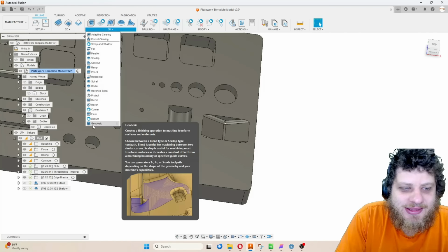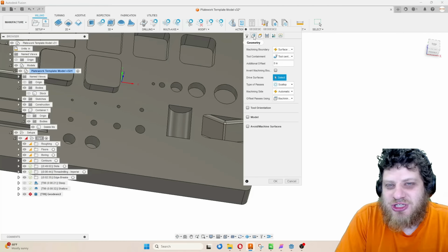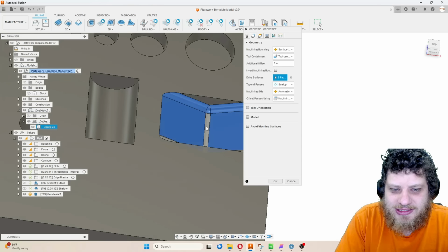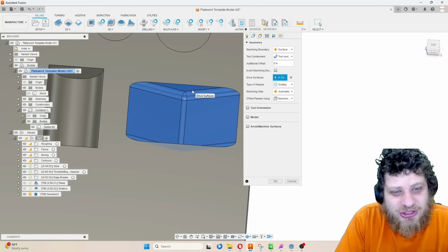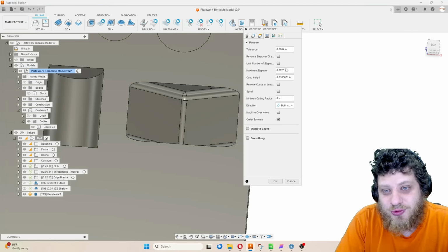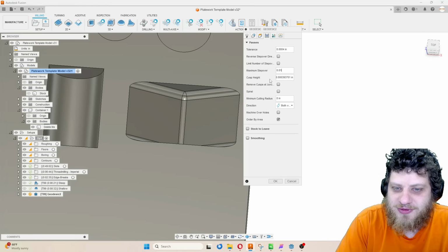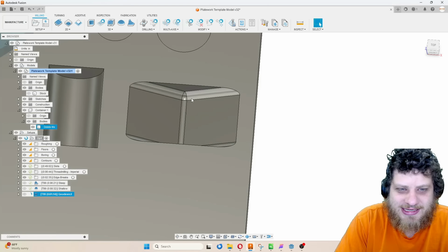And then lastly, there is one more toolpath that is frankly just magical, and that is this geodesic toolpath. With geodesic, you do have to manually select things, but once you select them, it does a pretty good job of giving you a pretty good toolpath without much effort. Just need to change my step over settings, select machine over holes in case that comes up, and this should give us something pretty decent.